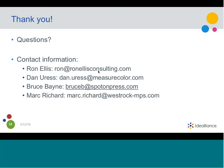In that regard, I remember I had a customer that had half the sheet with CMYK on it, the other half only had magenta, yellow, and black. And the pressman was complaining to me that he couldn't get the cyan to be consistent on that side of the sheet. And I asked him, well, what's the coverage on the sheet? What does the sheet look like? And he explained to me, you know, one side CMYK, good coverage. The other side just had magenta, yellow, and black and no cyan. And I said, think about it. And he goes, oh yeah, no coverage. If I have no coverage or very little coverage, I can't control the ink.